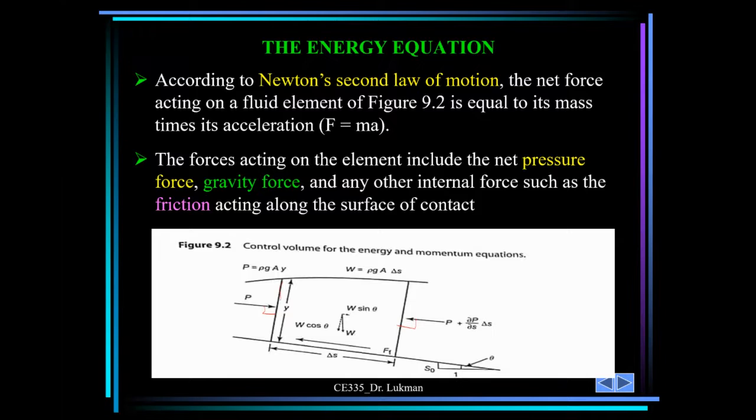The gravity force is simply the weight, because weight is the gravitational force acting on a body, and the weight will always act vertically downward. But the channel is inclined. You can see the slope, the angle is theta, and the bed slope is S0.